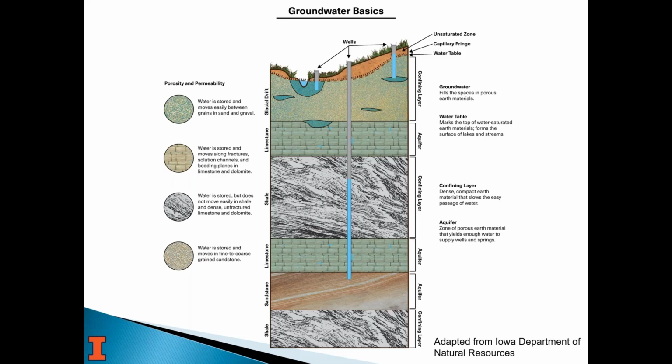But then as we go down, we start hitting different kinds of bedrock. Shale, looks like dolomite, and then there's a sandstone where the well's finished. But when you drill a well, and I'll show an example in a little bit, in bedrock, you don't case it all the way down like you would a sand and gravel well with a screen. You have to leave it open so that those fractures can get into the well borehole, right? And so usually you put a screen that's only seated a little ways into the bedrock, and then the rest of that is just an open hole. And because it's bedrock, it holds itself open.